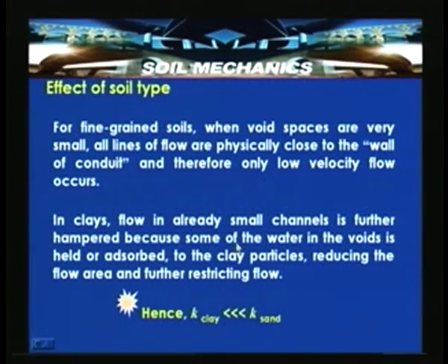In clays, flow in already small channels is further hampered because some of the water in the voids is held or adsorbed to the clay particles, reducing the flow area and further restricting the flow. So, in the case of clays or fine grained soils, the physico-chemical environment surrounding the particle influences the flow conditions. In the case of sandy soils, the frictional drag at the edges is not absent, except that the velocity is maintained and high flow is maintained.